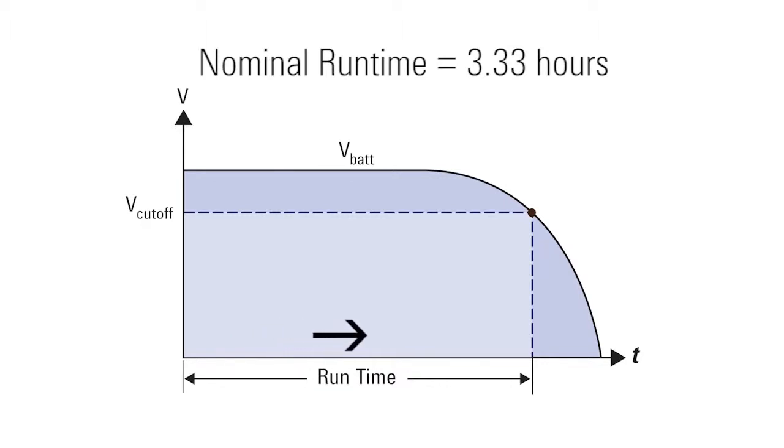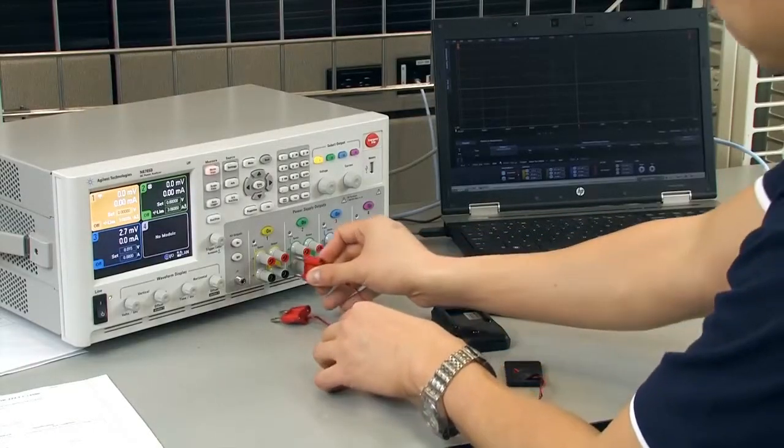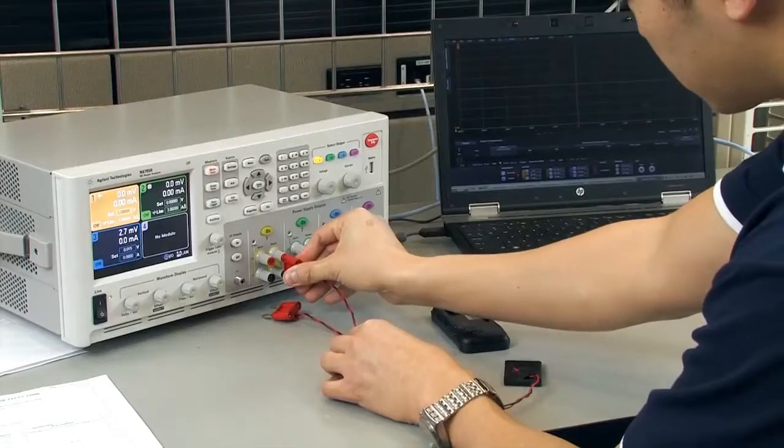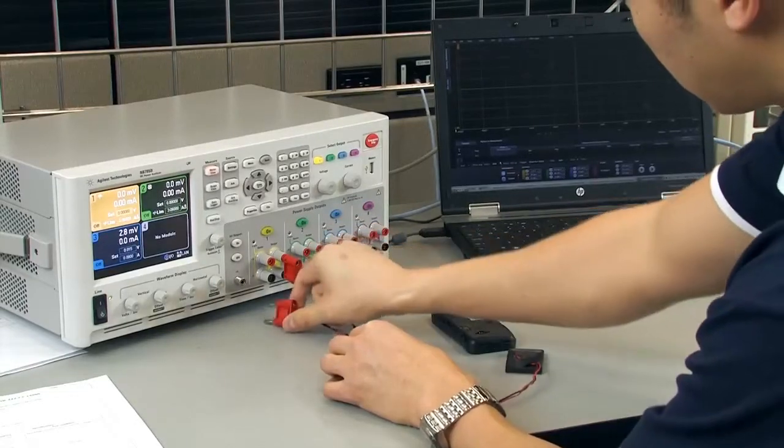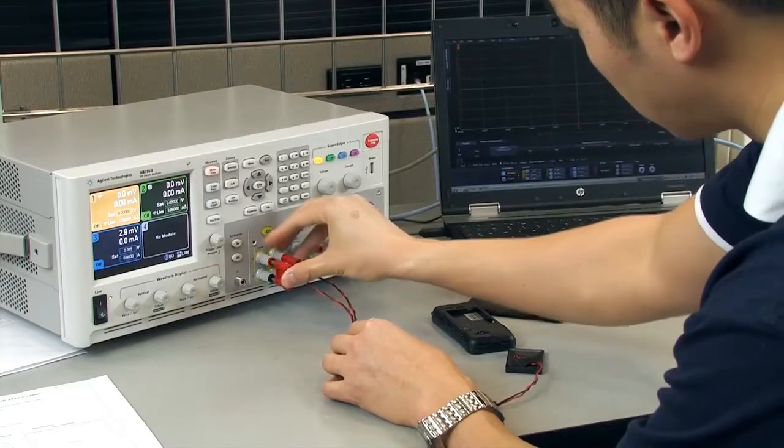It is also worth noting that the measured energy rating can differ from that based on the stated nominal voltage, as the actual battery rundown voltage profile may lead to a slightly different result. Precisely controlling test conditions while accurately logging both the battery's current and voltage assures accurate and consistent results when determining the battery's capacity and energy ratings.